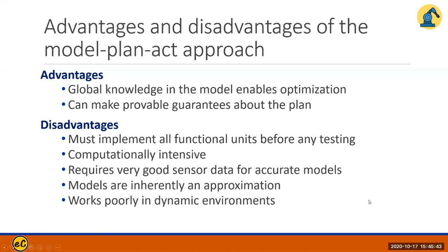So advantage and disadvantage of the model plan X approach. Advantage: global knowledge in the model enables optimization, can make provable guarantees for the plan. And disadvantage: must implement functional units before any testing, computationally intensive, requires very good sensor data for accurate model, and models are inherently an approximation. It won't be optimal, and works poorly in dynamic environment. So if people change the maze, you cannot solve it.